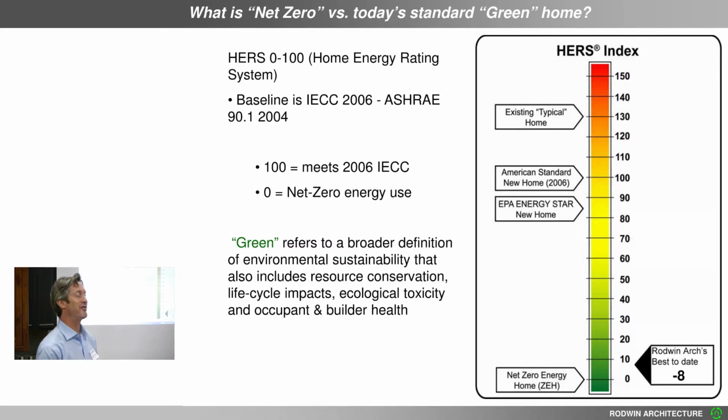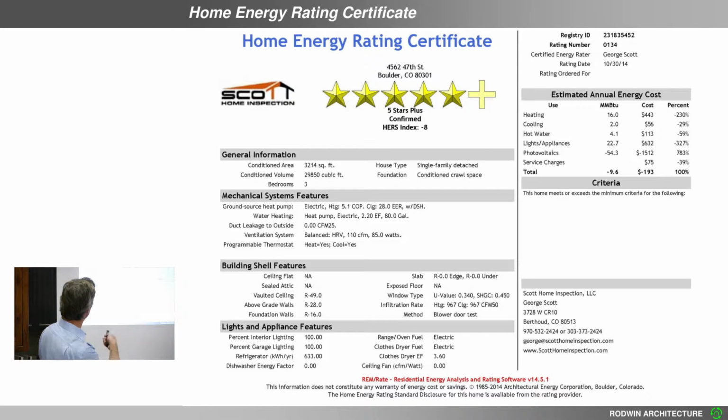If I say this house has a HERS rating of 10, should I be proud of that? Darn tootin'. So just so you know, as you go to real estate showings, very often they will have a home energy rating certificate. And you'll see all these stars up here, and you'll be like, "Ooh, wow, that's great! It's 5.5 star." Just know that you can get a 5-star rating for your house with like a HERS 90. So don't be too impressed by the stars.